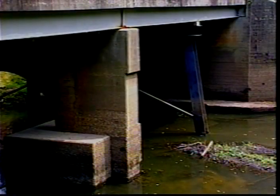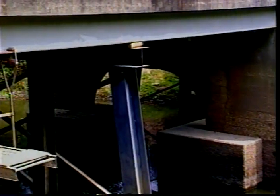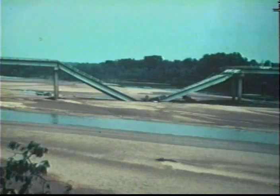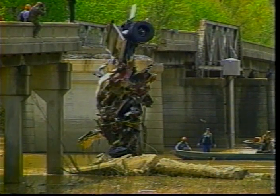Underwater members are highly affected by an adverse water environment. Moving suspended soil particles, debris, and wave action may cause the underwater members to deteriorate. Scour is a critical problem when the channel and foundations are inadequate. Scour causes bridge foundations to settle, and if conditions are very severe, the bridge can collapse. Scour is the reason for more than 50% of bridge failures. Scour and other underwater problems can suddenly appear even though a bridge has been in service for many years.